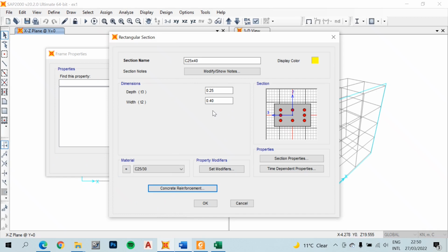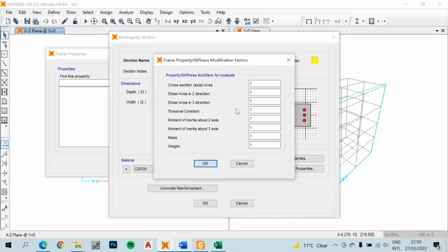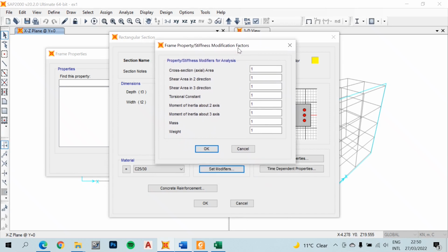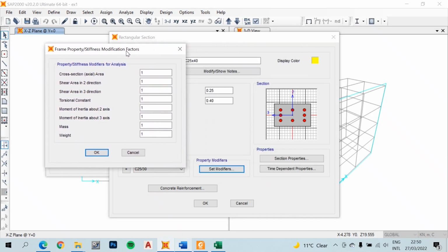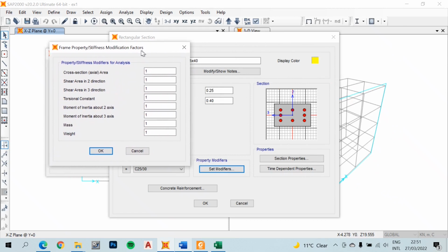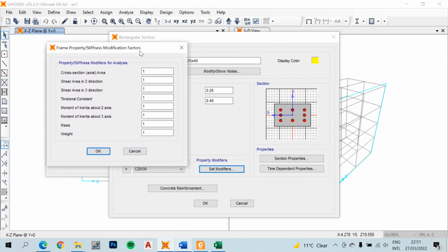And also there is another new rule that came in the new Turkish earthquake code, which states that you have to use the cracked properties of concrete sections. Which means that you have to modify the stiffness, or the rigidity, of your concrete sections, because we know that concrete performs very poorly in tensile stresses.